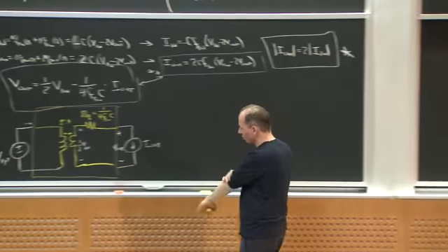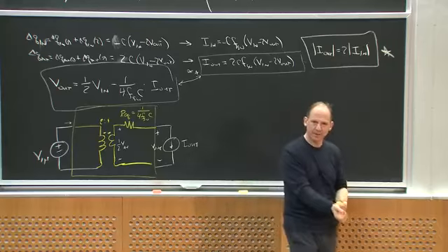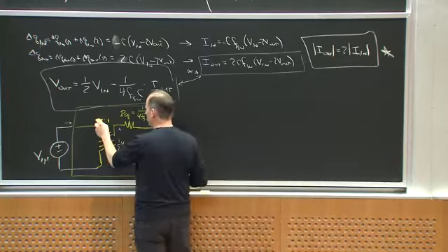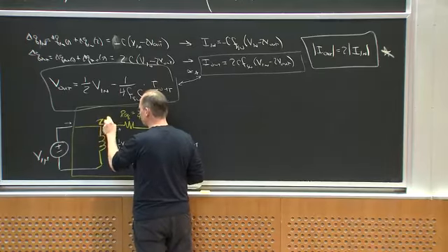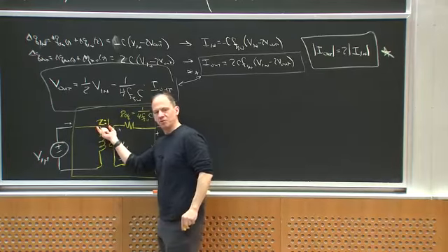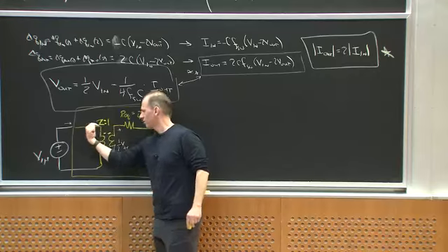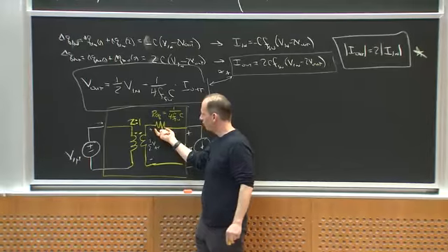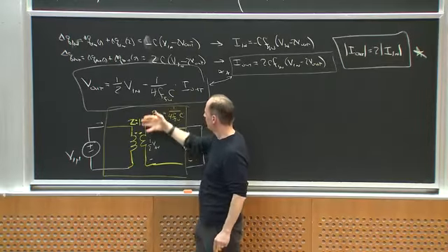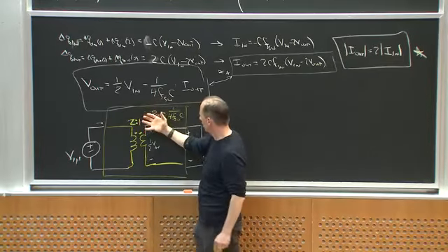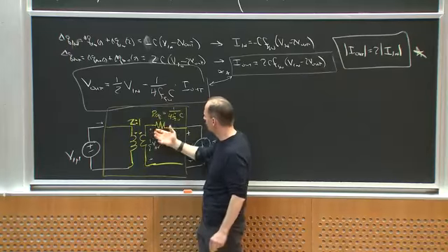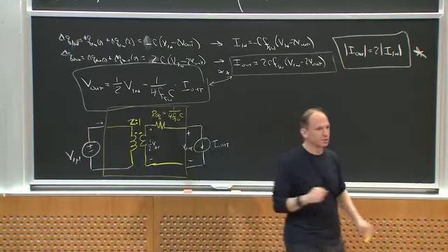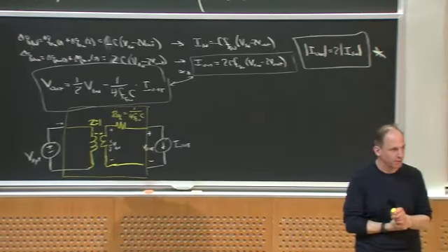Now, this is this converter. Any other switched capacitor converter I want to model, you can model likewise as some ideal transformer relationship. This gives me my current conversion ratio, right? The input and the output current are related by the ideal transformer, and then a voltage drop that's related by some equivalent resistance that's related to the energy transfer capacitors and the switching frequency. Okay, so the details will vary, but this model really captures what's going on.